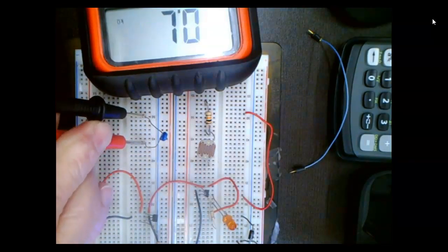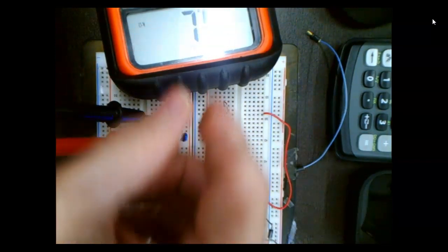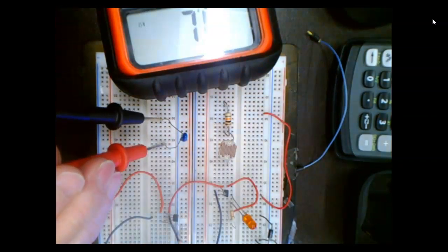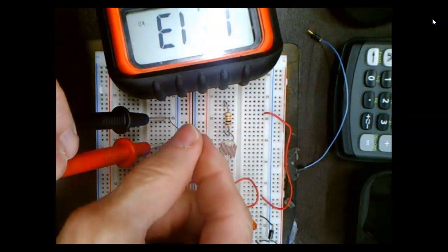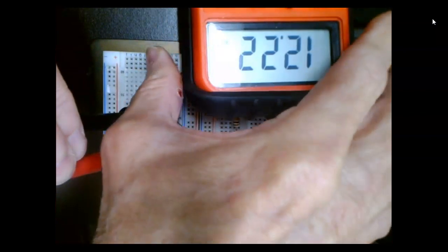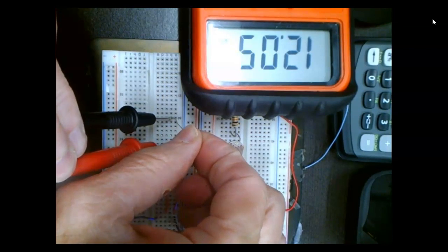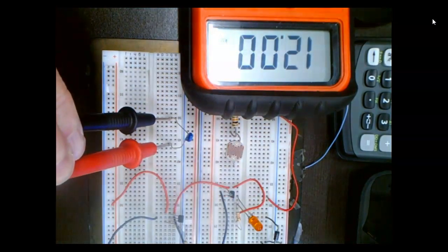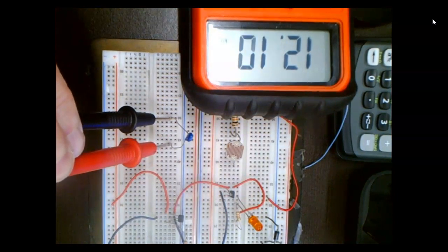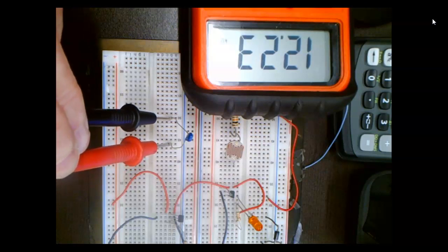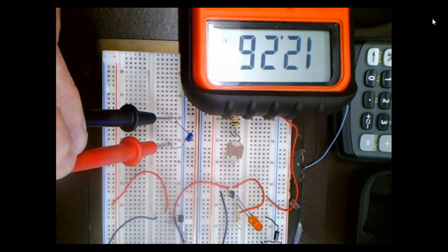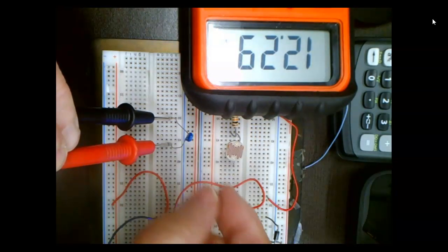And you can see as soon as I touch it, can y'all see that? I think we got a glare, guys. There we go. As soon as I touch it, the resistance starts going down. As soon as I let it off, the resistance starts coming up, right? You understand? So what would this be? Would it be a PTC or an NTC? Yeah, NTC, because the resistance goes down when temperature goes up.